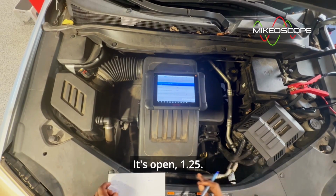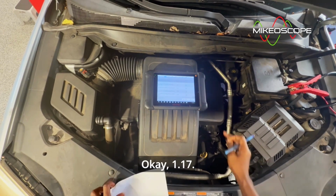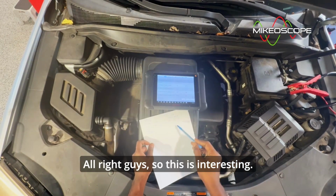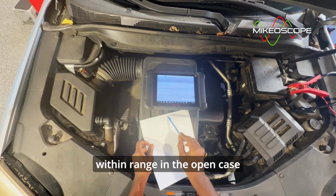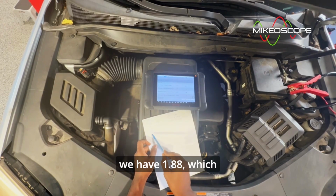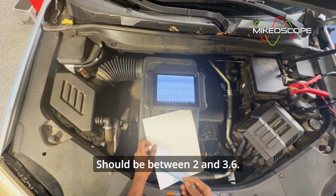It's open, 1.25, okay, 1.17. I think the max we saw was 1.25. All right, guys, so this is interesting. The max delta pressure we saw was 1.25, which is actually within range in the open case when the valves are open. Now, if we look at the closed case again, we have 1.88, which should be higher than that. It should be between 2 and 3.6.